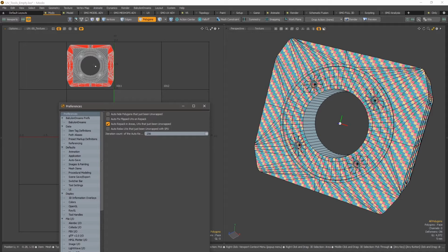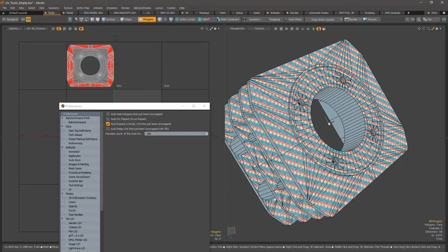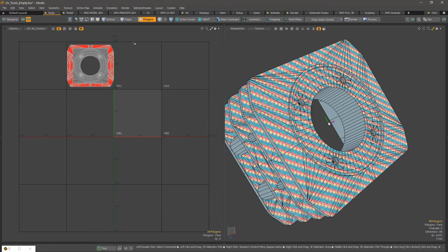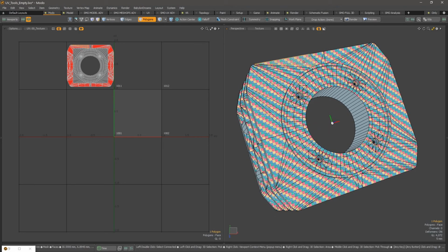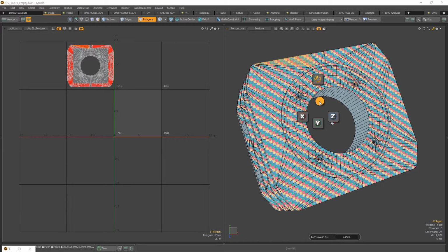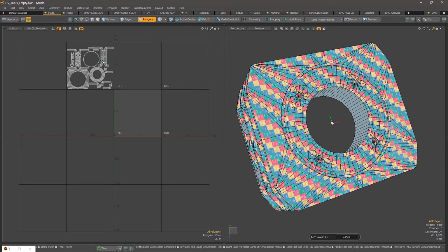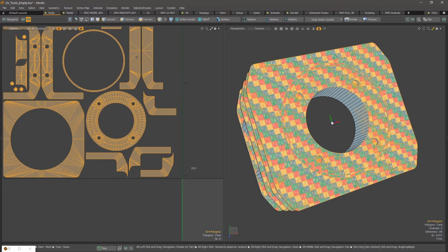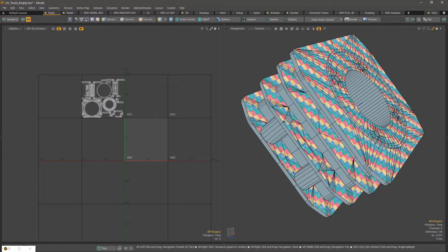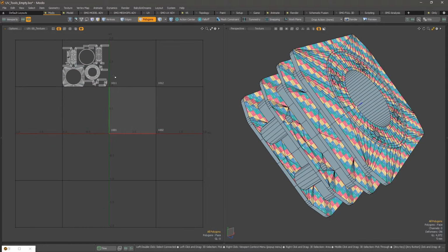So as I've made the repack, the unwrap, also it didn't hide the elements unwrapped. So now I will check just the repack to show you the effect of this. So same thing, I select one polygon, press Q, go to Smart Projection Planar, and we'll do this on the object on the Z axis. And now we have packed elements over here. So it just automatically repacked the elements over there.